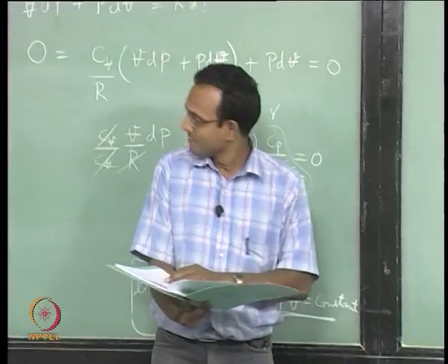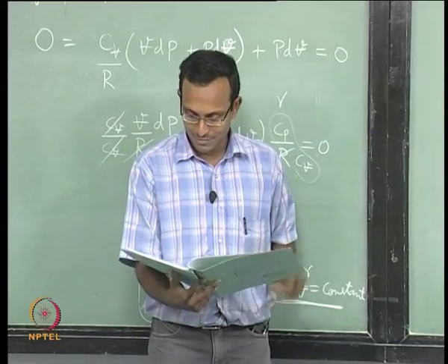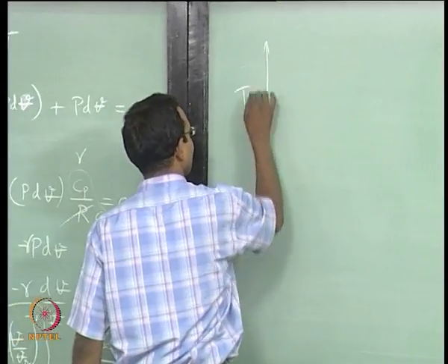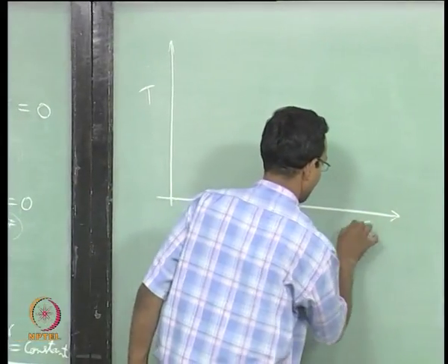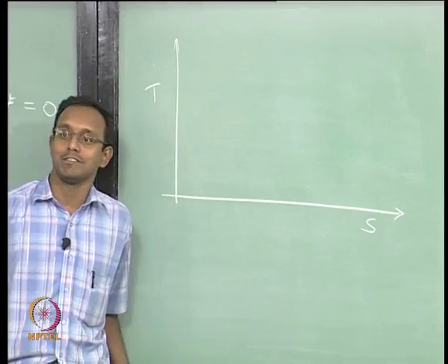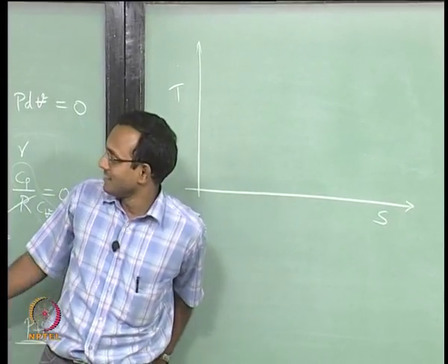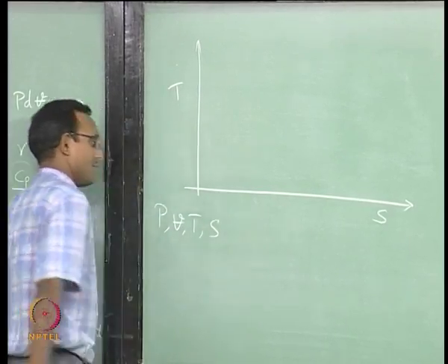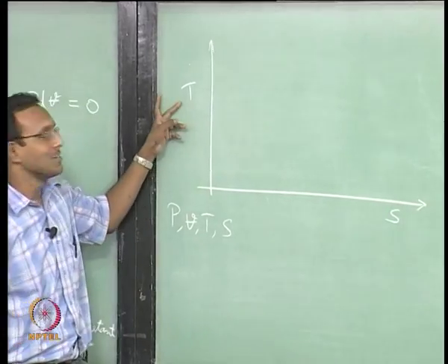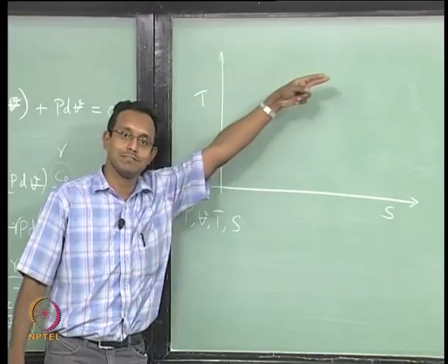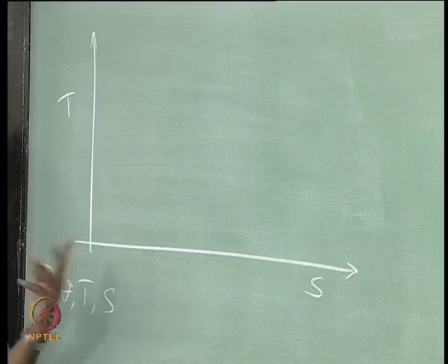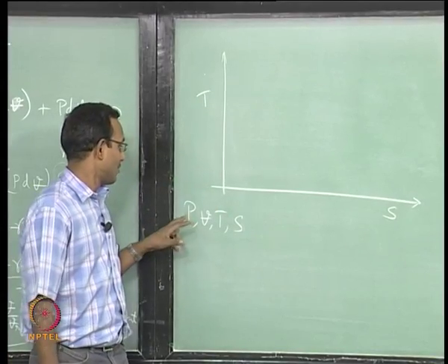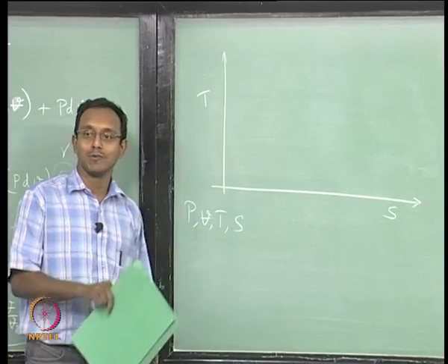Now this is a simple thing, we just did the PV diagram. Next, let us say we pick a TS diagram. Temperature and entropy are the variables now. We had those 4 variables, right? If I want to talk about a constant temperature process, of course it is a horizontal line. If it is a constant entropy process, it will be a vertical line. Simple stuff, no point drawing it. What if it is a constant pressure or a constant volume process?